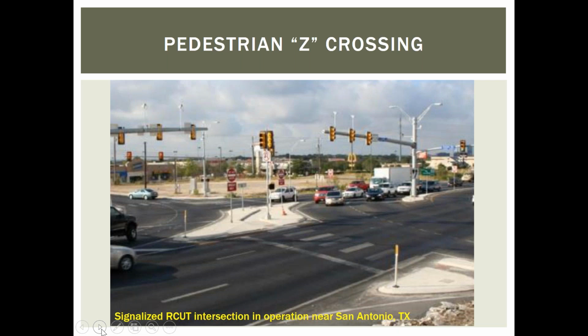However, when the pedestrian is in the center there, that is the same time as when the left turning vehicles are stopped. So you may think, well, I'm putting pedestrians in the middle of a busy highway. Well, yes, but it's one of those things that until you experience it as a pedestrian, you've got to experience it to believe it.